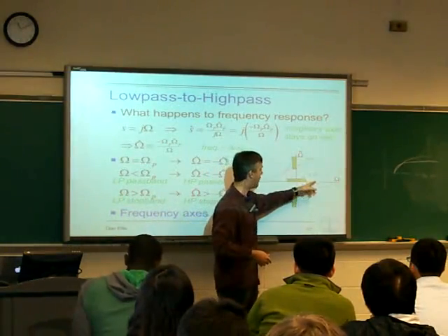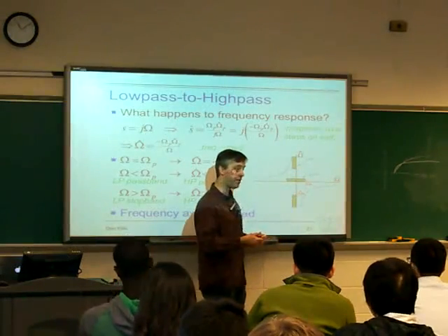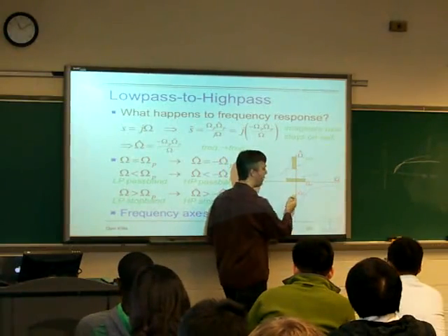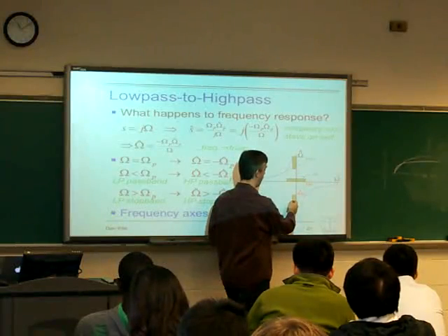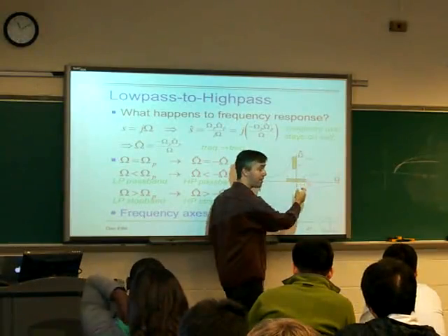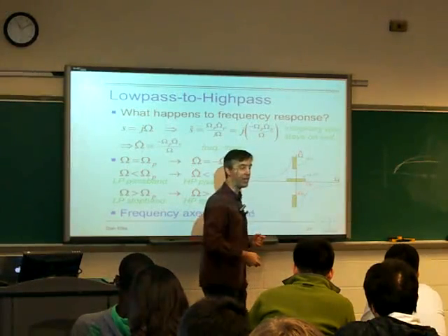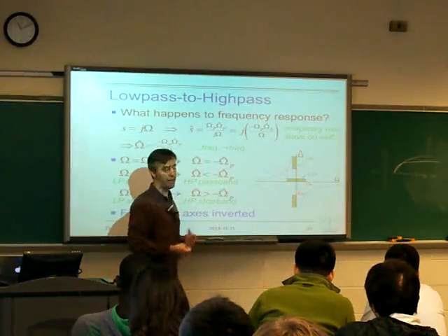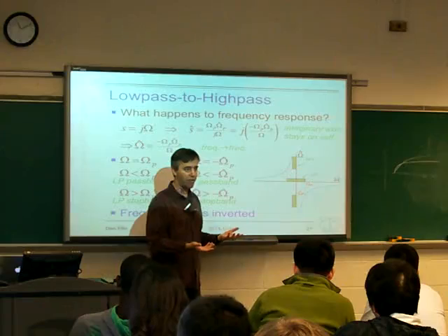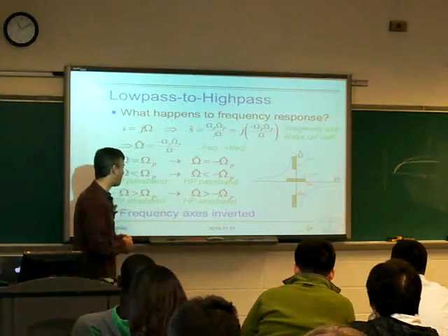And so that's the actual point where, if we have a particular value, if we've got this transformed system, we have some frequency, we want to know what its gain was at that frequency, we can literally just go here, look up the omega p that corresponds to that omega, look at the omega that corresponds to that omega hat, and then read off the H of s for the original filter at that frequency. I mean, that's what our transformation did, but we can relate them like that.